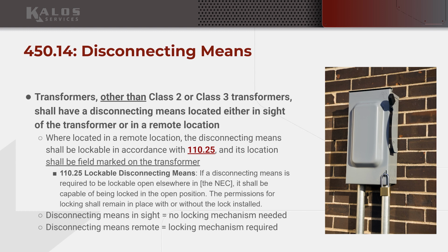And so this is something also I think we're missing on a lot of our transformer installations: we aren't putting proper labeling on that transformer, because in almost all scenarios that we have in our stores, our primary is coming from a circuit breaker in some remote location far away, and we are not installing a safety switch on that primary before it enters the transformer.